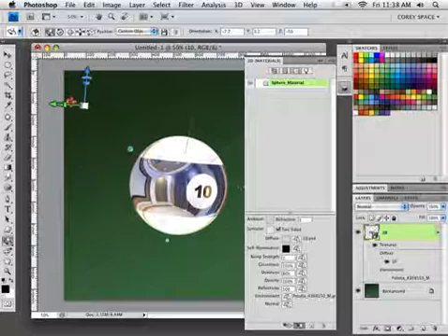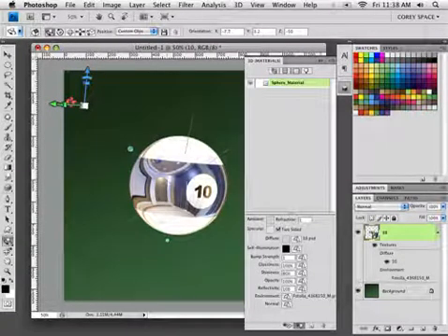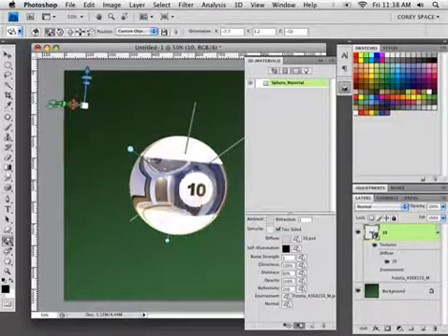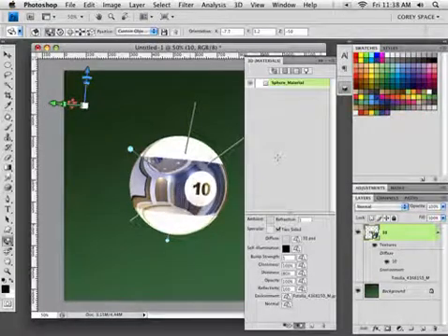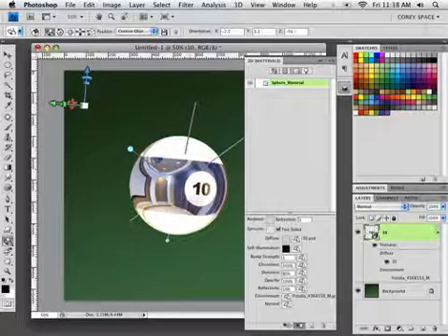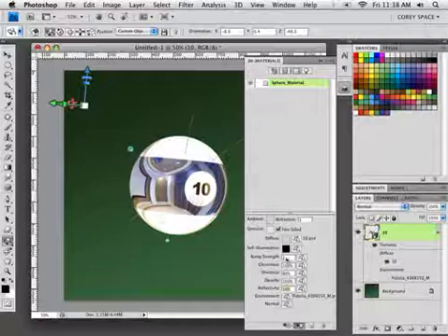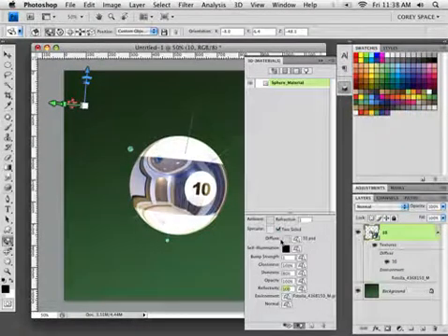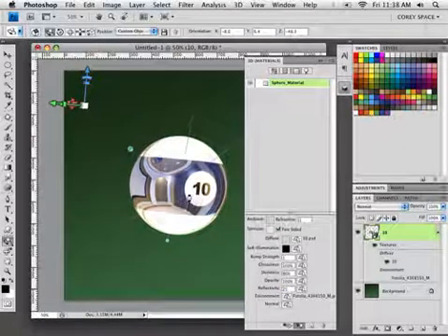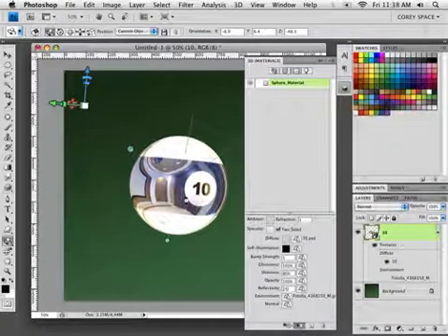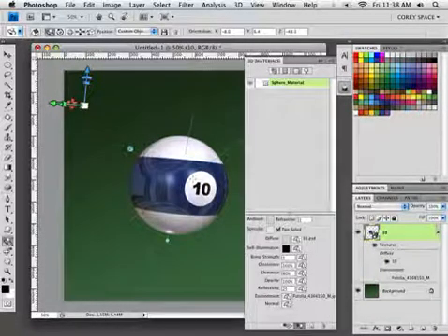It's going to take a minute. It's going to apply that texture to my image. Now, if I rotate the ball around, you'll see that the texture is staying put as if it were reflecting in the real room. It's probably considerably intense, so let's take the reflectivity down to about 25, and that will redraw it and make it a little less intense, allowing that color to go through. There we go. That looks better.